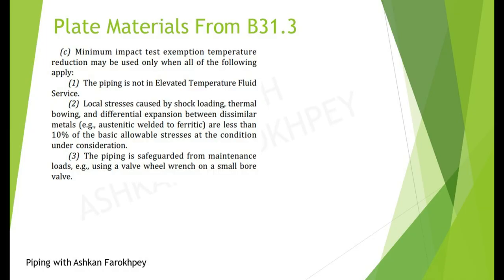Note C is for making sure that the material, which can be a valve body, fitting, flange, or even a plate material, is not planned to be used in severe operational and maintenance conditions. For example, conditions such as high temperature, local stresses, or high maintenance loads such as a high torque required for closing or opening a valve during low temperature operation.